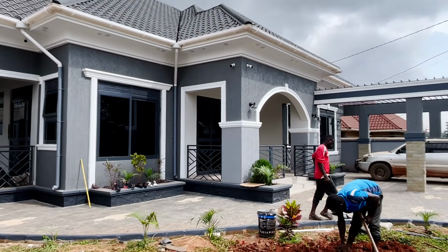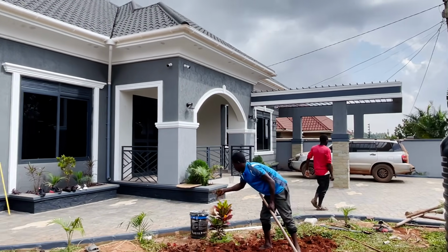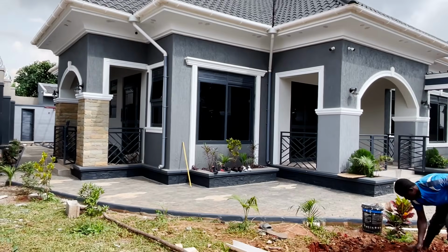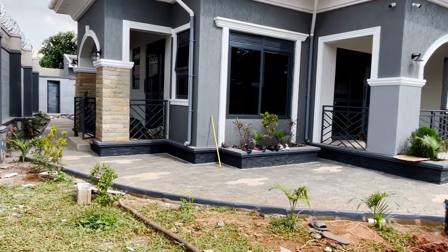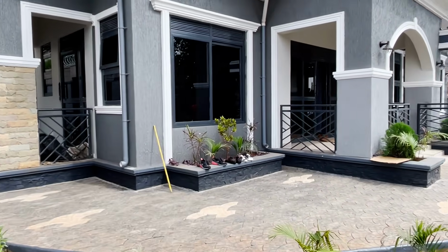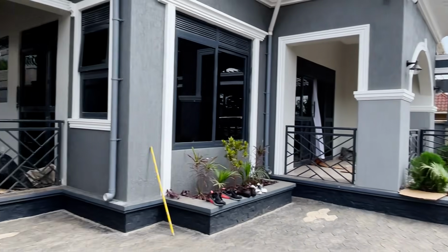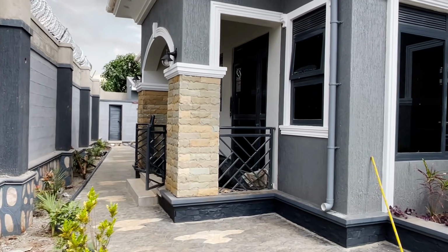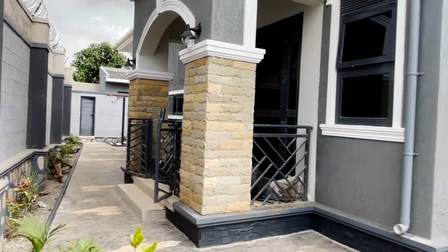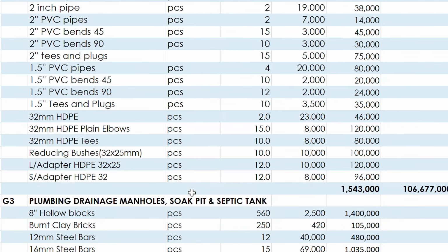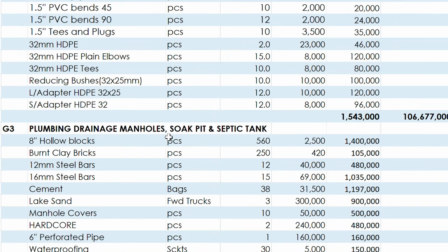But they had put the septic tank option just in case someone who will live in that house does not know the rules and regulations of how someone is supposed to use those plumbing appliances when using a biodigester septic tank. So they decided to install a normal septic tank, which can be emptied when it gets full, usually about 7 to 15 years, depending on the usage or the number of users.